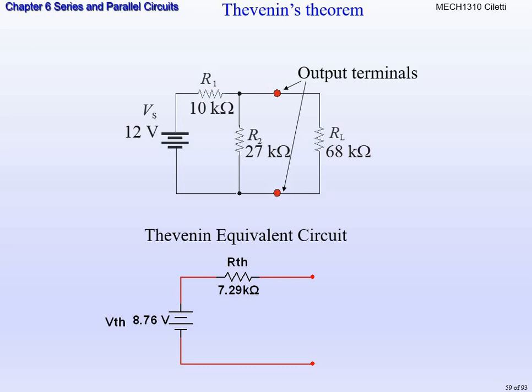So the solution, we would draw it as this. On top, that's the original circuit, the original schematic of what we had. And the bottom is our Thevenin circuit, where we have found our Thevenin resistance and our Thevenin voltage. This goes back to when we started this lecture talking about looking from a specific terminal, what does it see? We don't care what's inside the box. It sees one resistance and one voltage. So that's why we make this Thevenin circuit.